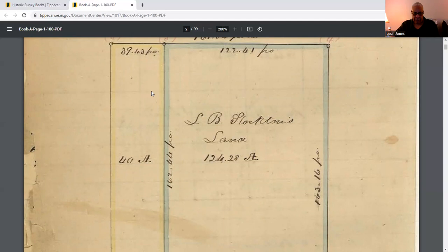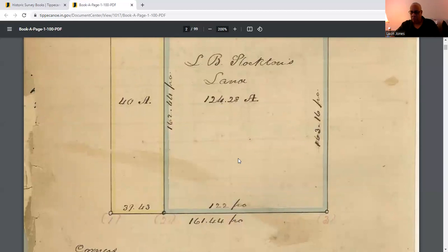This is 40 feet here, and this is 126 feet. Now, again, in those days, you had chains. 66 chains. And a real chain, that's what you use. Now, today they don't use chains. I know when I started surveying, I used the steel tape. Problem with the steel tape is you have to be careful, because when it gets hot, it expands. So one of the reasons why this system was created is to make sure that everything was accurate and you could make corrections.